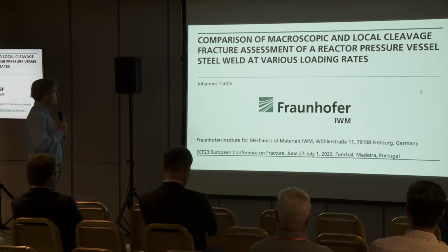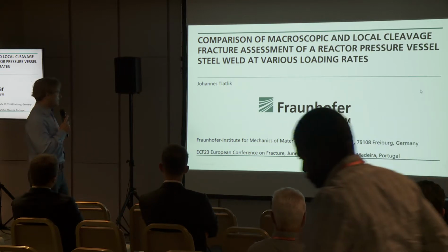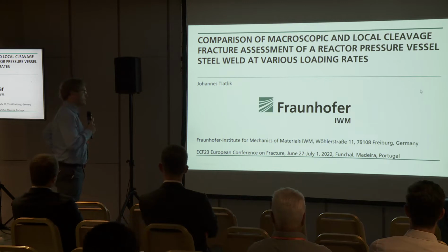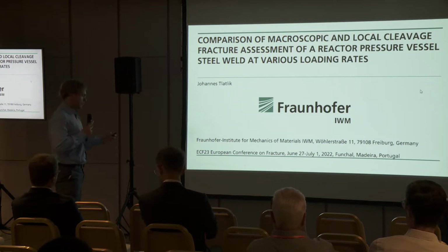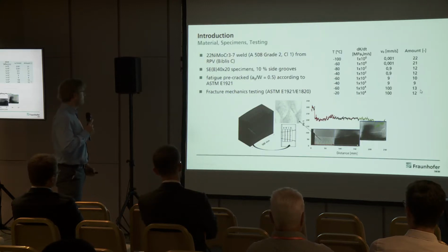Basically, what I'm going to do is analyze a reactor pressure vessel steel weld by the master curve concept, and also use a local approach and just compare what the assessment methods say for various loading rates. Something really interesting happens there, especially at higher loading rates.